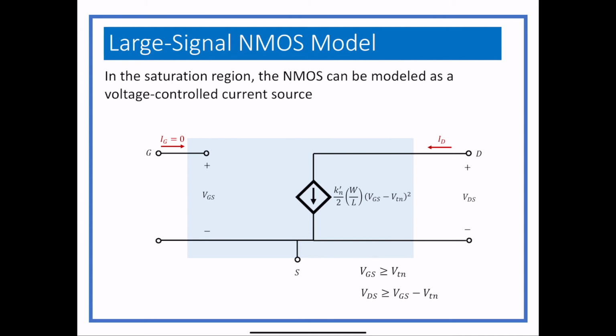The problem is it's not complete. There is one other part that has to be added to make it complete. If you're able to take a MOSFET and create characteristic curves, which is hard to do because MOSFETs get hot, and when they get hot, they stop doing what you want them to do at all. I think in lab you do make characteristic curves, but they just look like lines at a couple different places because it's not as easy as doing this for a bipolar junction transistor. You can get the characteristic curves by hand, and it's not that difficult to do. With a MOSFET, depending on the MOSFET you have, it's much more difficult.